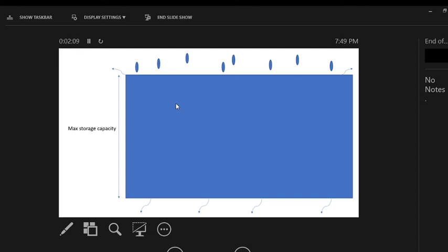And again, as we talked about evapotranspiration before, once the rainfall ends, then you'll begin to regain the storage capacity through that evapotranspiration process. So hopefully that gave you a little bit of knowledge into this process of infiltration, and also maybe a little bit more knowledge about the parameters that are used in the deficit and constant loss method that's in HMS.